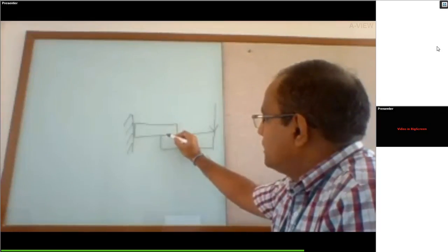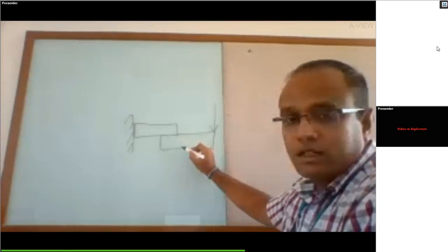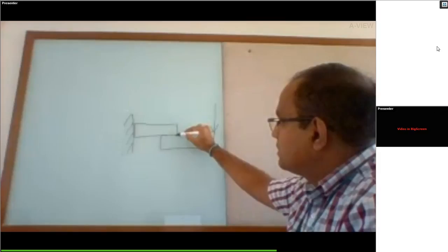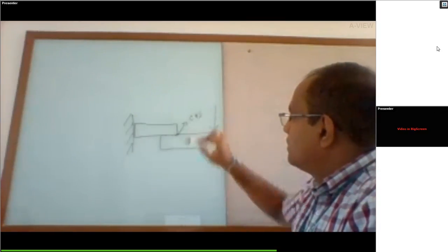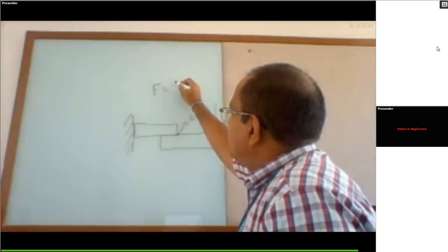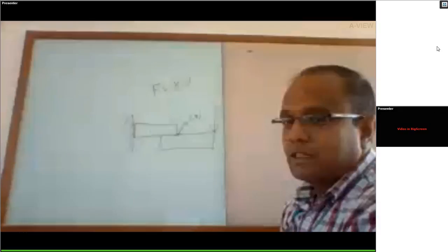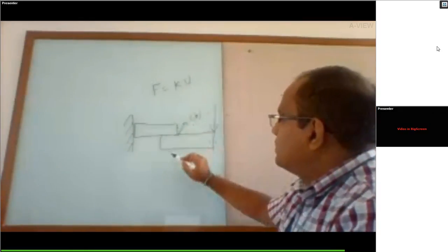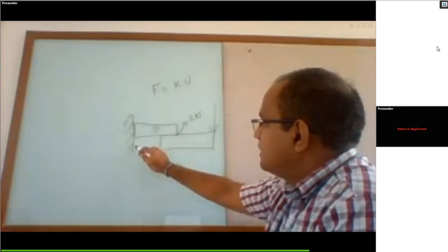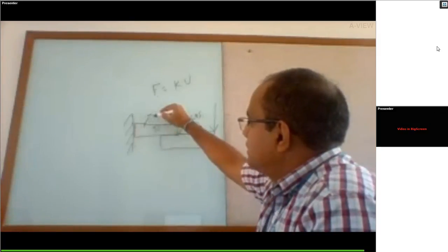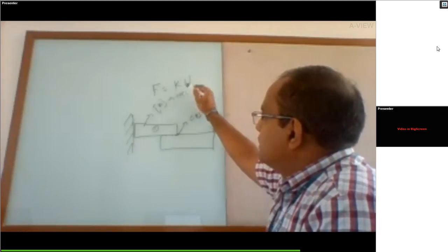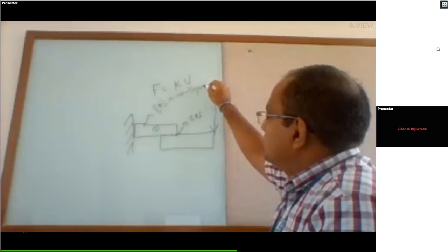Here we have used couplings. These two components are tied at this location. This is CP. As per our finite element equation F equals Ku, when there are no constraints, this K will be singular. Let us take component 1. This component is constrained here, so its stiffness matrix is non-singular. The singularity is removed.